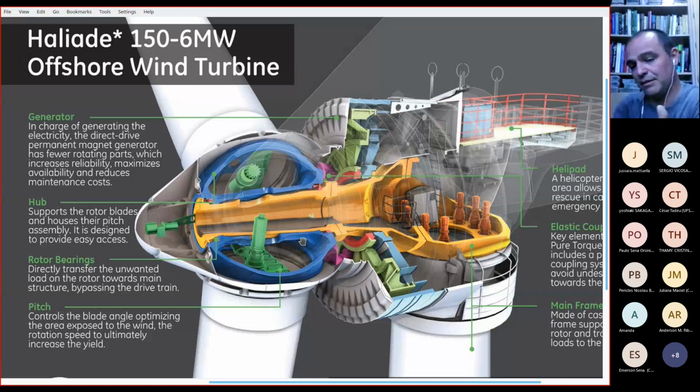These gears work at low speed, but still, how many teeth do we have on the yaw control? And perhaps you see here in this picture how many motors are controlling the yaw. We have 7 motors controlling the yaw. What happens is if one of them fails, the load will go to the other 6. What happens if another one fails? Okay, we have 5 motors controlling yaw.